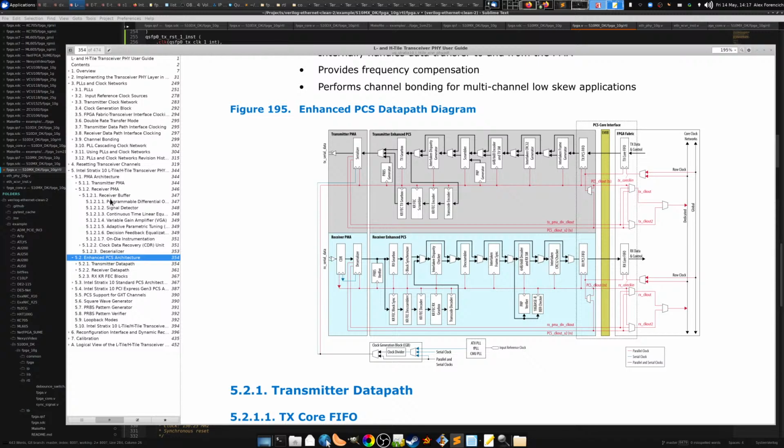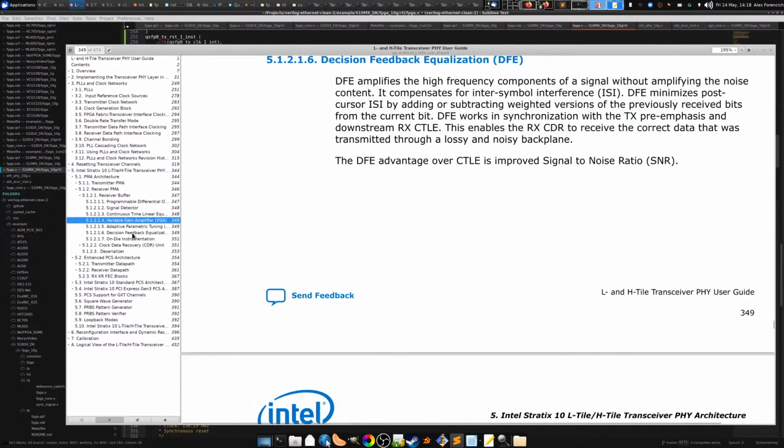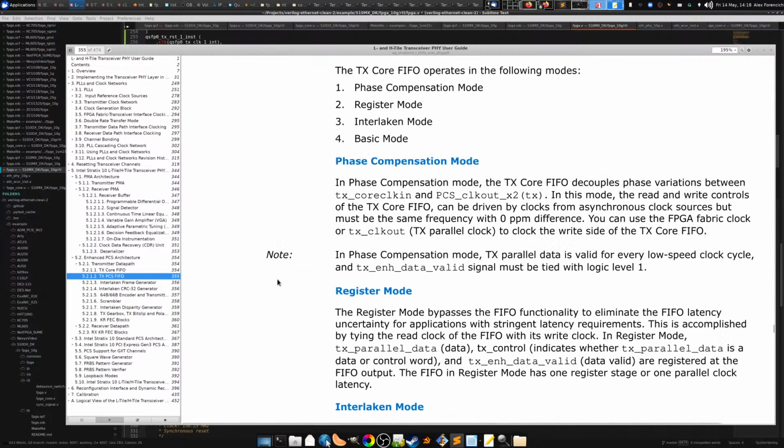This is kind of an important characteristic, because the way 10G Ethernet works, it moves around these 66-bit blocks. But on the deserializer, you basically need to find the 66-bit blocks, because it's going to lock onto the data just somewhere, and it's not necessarily going to be aligned with these blocks. So what you have to do is what's called bit slipping, where you slip the gearbox by 1 bit position until the block lines up. And there should be, I'm trying to remember where this is in here. There is a description of the timing that's required for that.